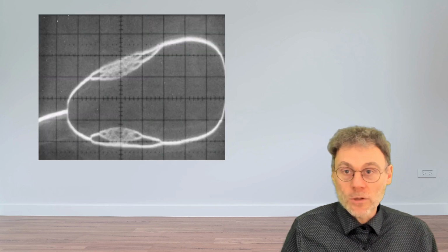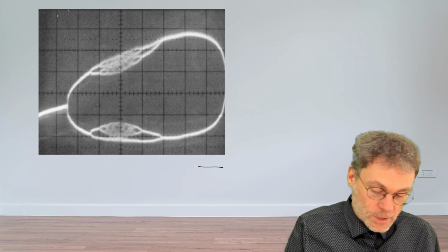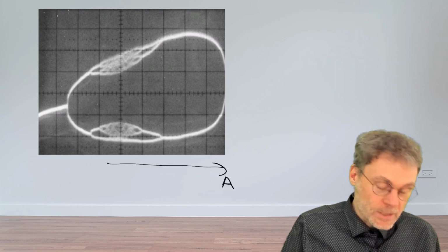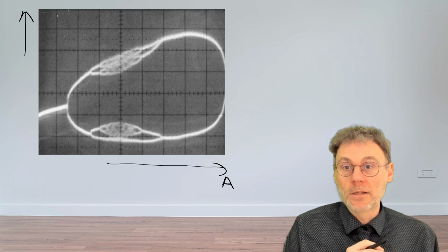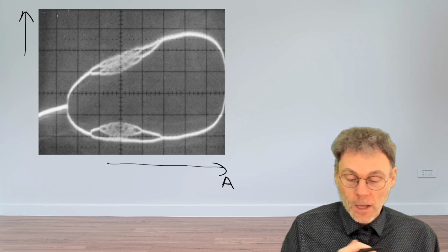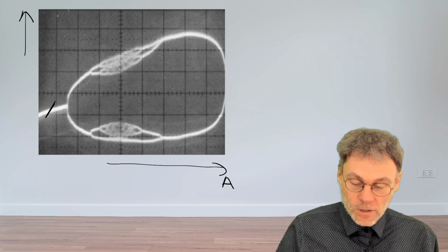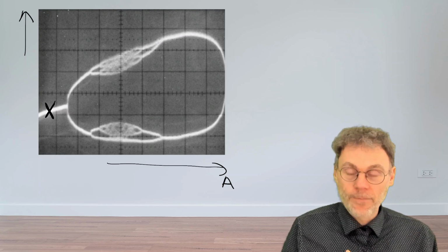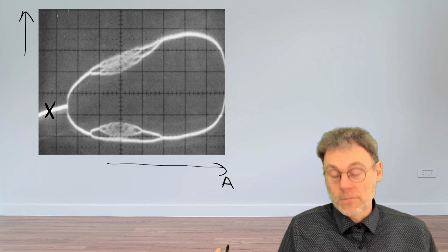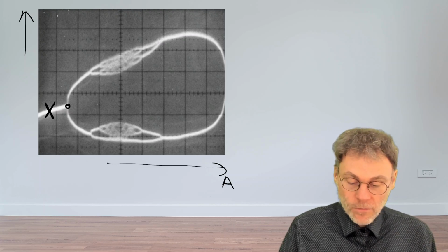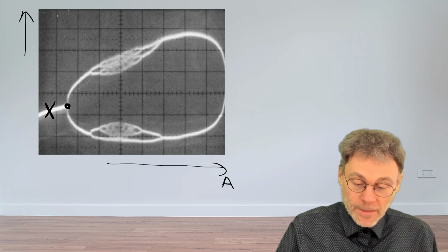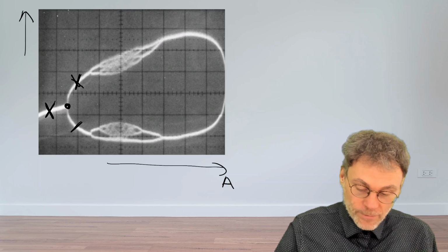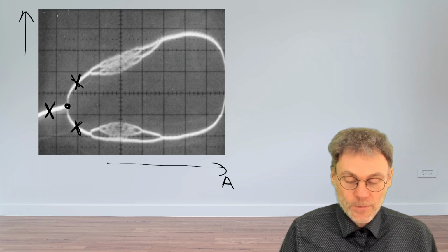So if we look at the actual experiment that people did, this is the way they hooked up their oscilloscopes. On this horizontal axis, they had this offset A, the DC offset A, and here on the vertical axis, they had the different points that they sampled. So you see in this initial region over here, they just had a single sample per bit period. Then at a certain point, once they crossed this threshold over here, which is a very important situation, they ended up in a situation where you have these 2 samples. You can clearly see the 2 samples per bit over there.